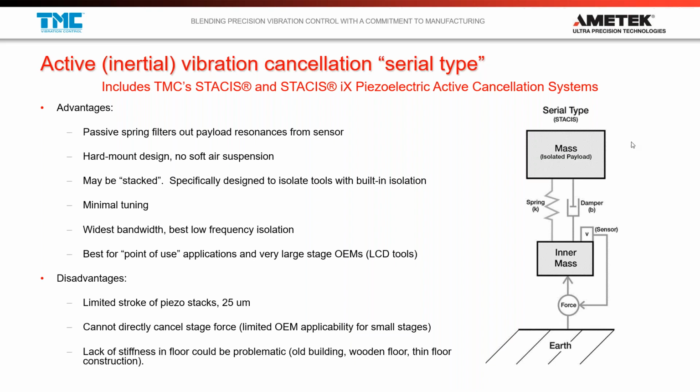And also, there's very, very little payload noise coming into the inner mass. Therefore, the sensor is free to really cancel out only what's sensed on the inner mass, which is only what transfers through the stiff actuator that's supporting it.